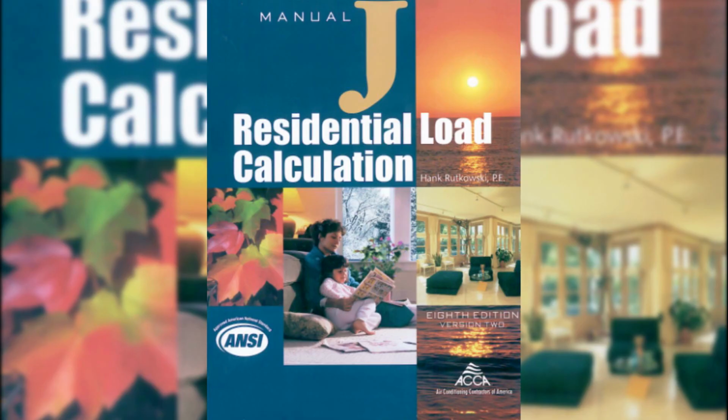Efficiency doesn't automatically mean comfort. In fact, the most common complaints in high-performance homes aren't about energy bills. They're about drafts, uneven temperatures, and stratification. That's why following the fundamentals in ACCA Manual J for load calculations, Manual S for equipment selection, Manual D for duct design, and especially Manual T for air distribution is critical.